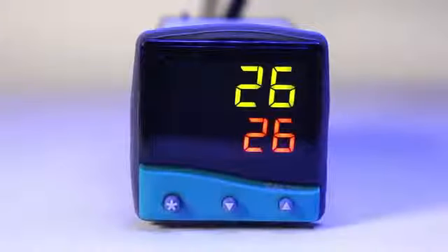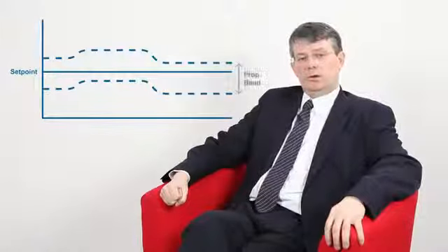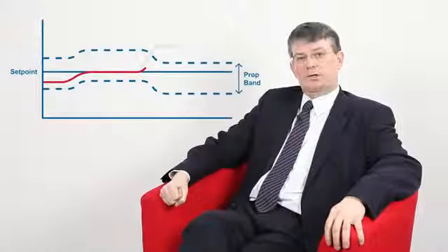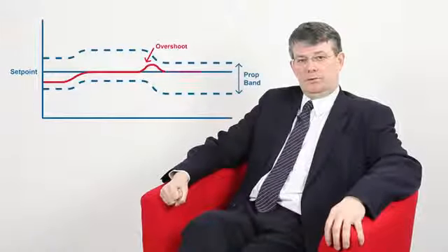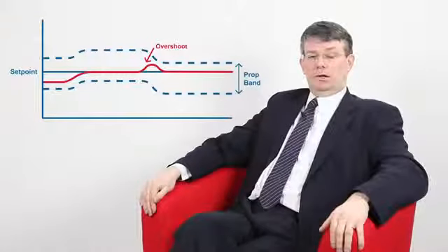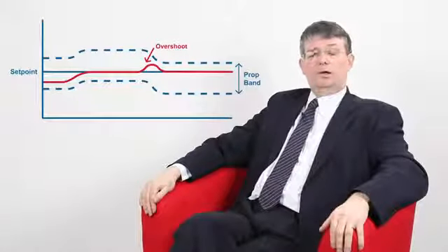If some overshoot beyond the set point was to occur, the direction of the integral action would reverse. In this case, the integral action would bias the working point lower, reducing the power put into the process and starting to eliminate the positive error. So you can see that integral action is just doing automatically the reset function that the user had to perform with proportional only control. And for this reason, it is sometimes referred to as automatic reset.